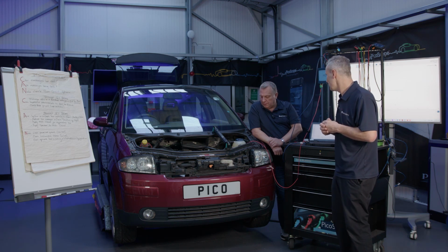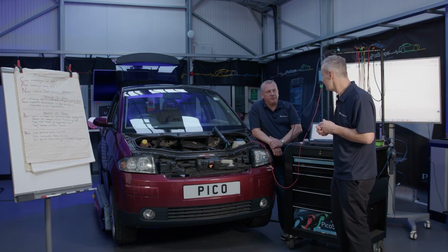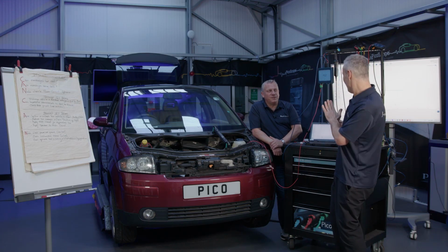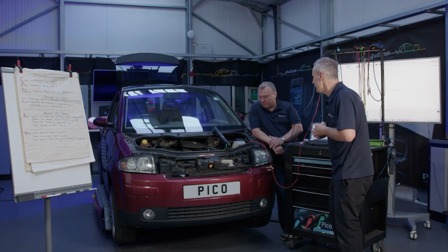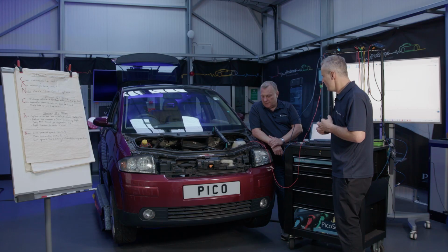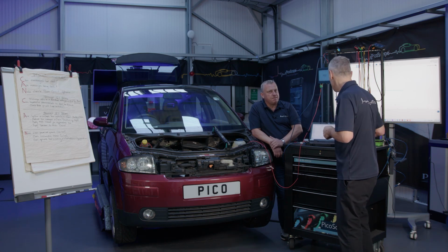Tolerances, yeah. But obviously it depends on one big variable, temperature. Temperature, of course. Length of the conductor, and cross-sectional area. All of those things will affect the resistance of a conductor, besides all of the other influences such as connections. But in your experience, would you go 57, I'll accept that? A general rule of thumb, 10%. So we're going to plus or minus 6 ohms at this stage, and we'll move on.